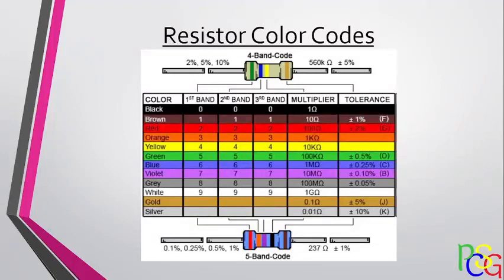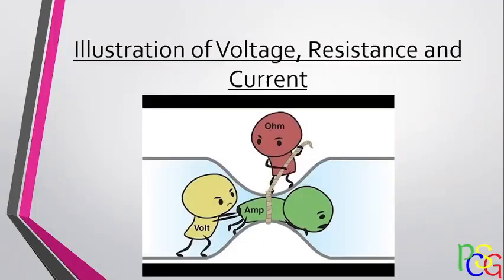So whenever you see something close to a set resistor value that you know exists, for example, a resistor that's supposed to be 1k and you measure it and get 998 or 990 ohms, just know that it is a small margin of error, and it's not going to be the make or break of your circuit. Good. So now we've covered the resistor color code. It's something you need to know, because as we go along, I may bring it up in an exercise or a test that we may have.